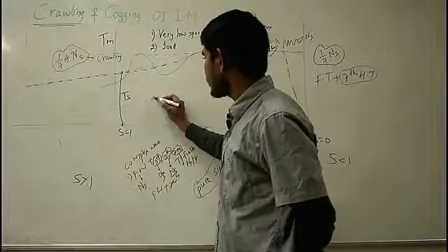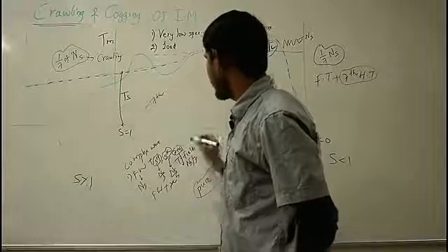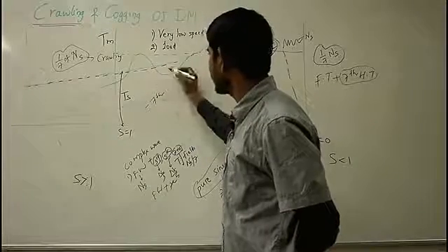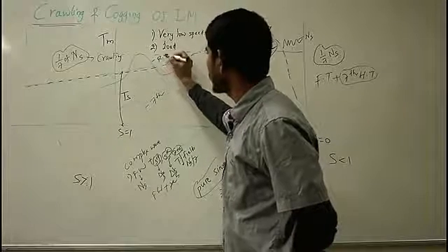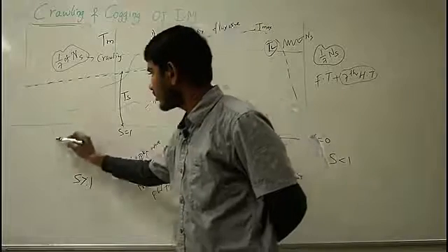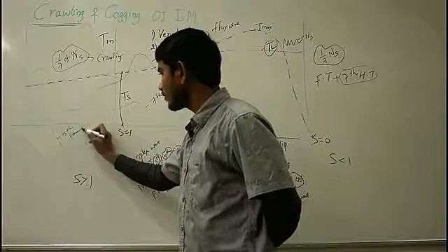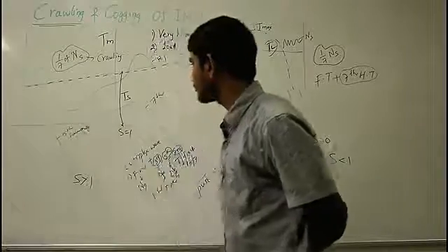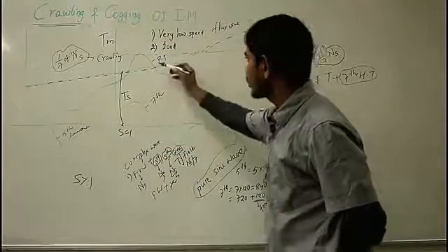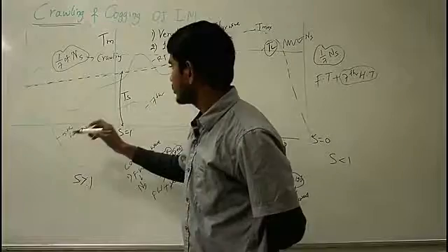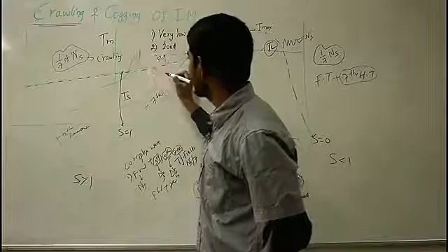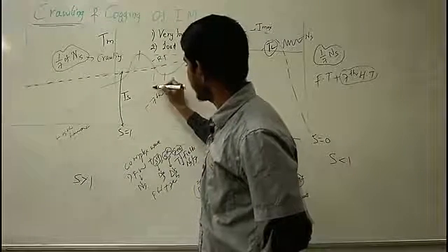So, this is your 7th harmonic, the 7th harmonic like this. This is the resultant torque, and this is the 5th harmonic. So the resultant torque will be like this, and if you see, this region is known as the stable region.